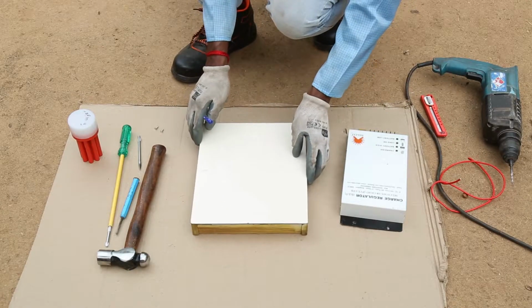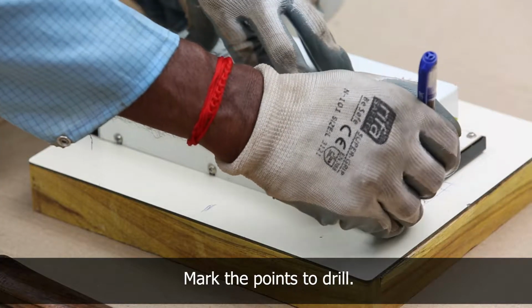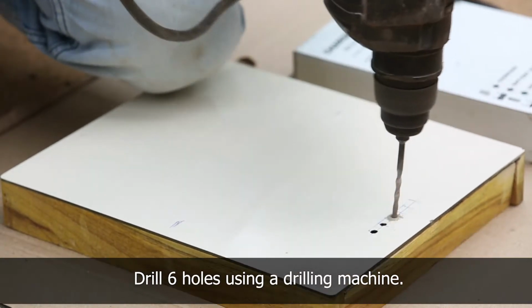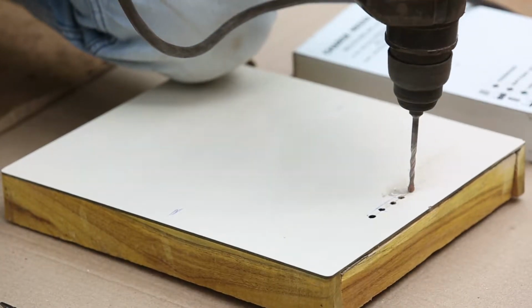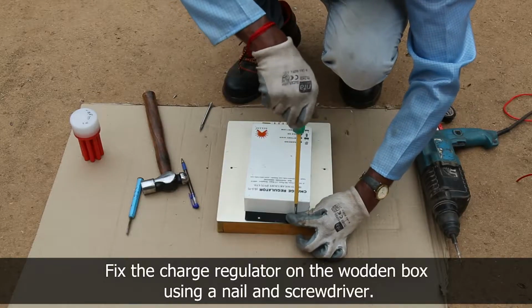Now, to connect the charge regulator, keep the charge regulator on the wooden box and mark the place to drill holes for wires. Use a drilling machine and drill 6 holes to connect the positive and negative wires from the solar panel, battery and load. Fix the charge regulator on the wooden box.